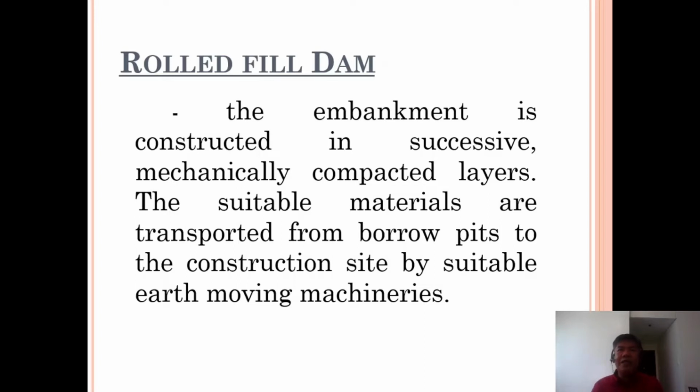What I have is those temporary dams, like the temporary cofferdams, when we constructed different structures in the Sultanate of Oman, like the shipyard, the dry dock, and the power plant, because some structures are located in the sea area, surrounded by water. To block the water while you excavate for the foundation, you have to construct temporary dams. We call those temporary cofferdams.